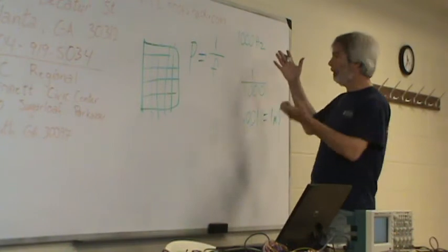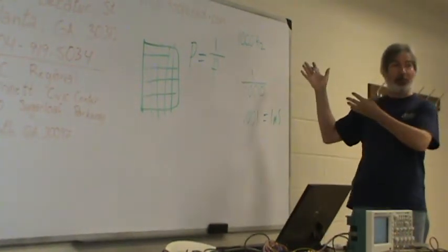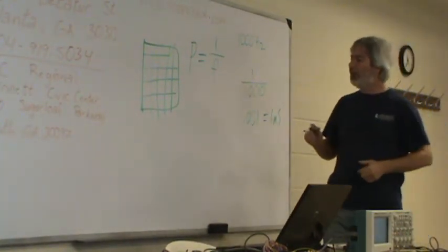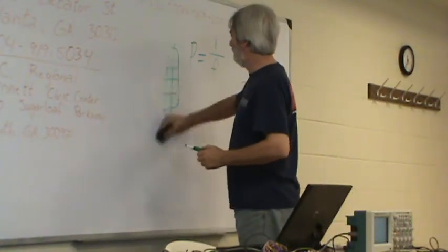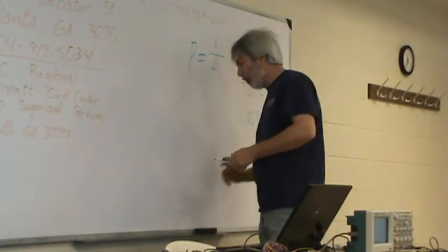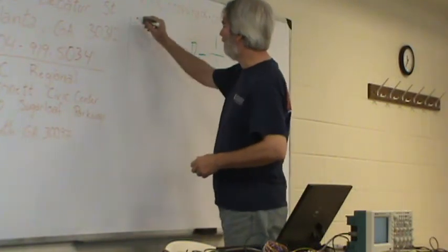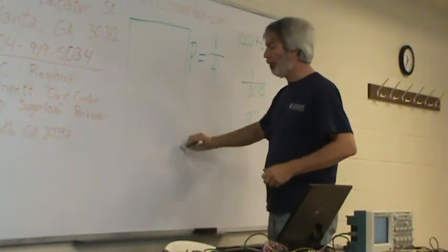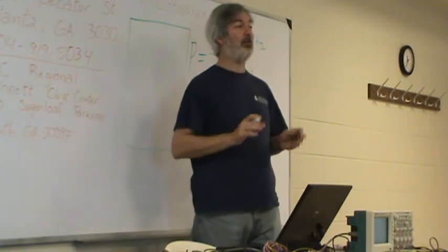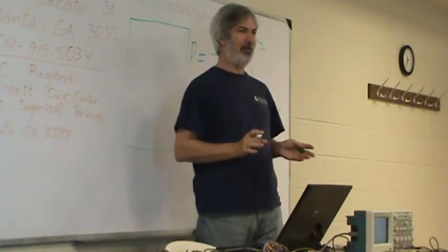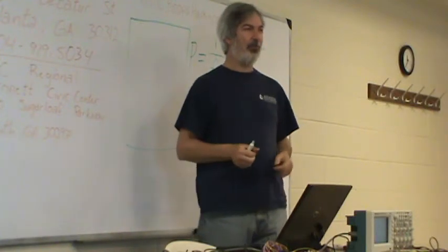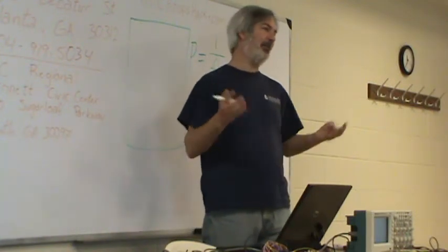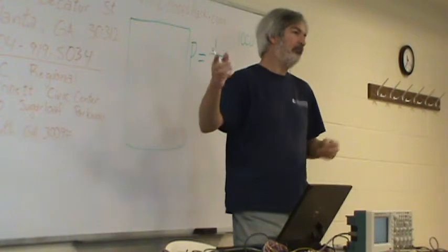Yeah, well, okay, let's say you're building an oscillator that ideally is 1,000 hertz. On paper, it should be putting out 1,000 hertz. So, let me draw this a little bit bigger. What you'll do, you'll have your scope screen. I'm going to assume that you're using a good old-fashioned dumb scope. Because the easy answer is if you use a digital scope, you get it on the screen, you push the button, it tells you it's 998 hertz.